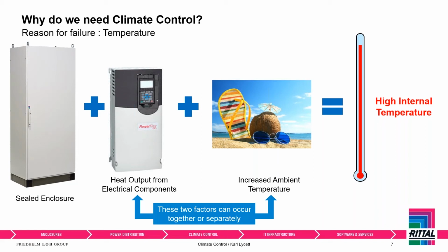And on the flip side, you might only have some switchgear or some PLCs in there which don't really kick out much heat. However, it might be just really hot in your warehouse, your workshop, because you've got so much equipment crammed into a small space and you've got a poor level of HVAC equipment. I see this all the time when I used to visit sites, when we could, and obviously will do in the future.